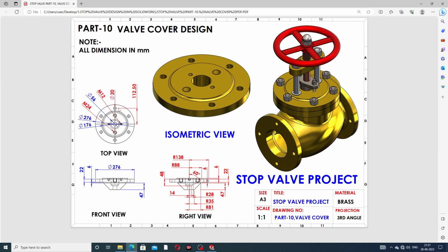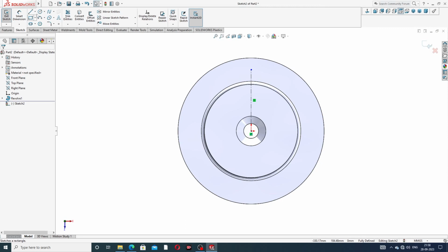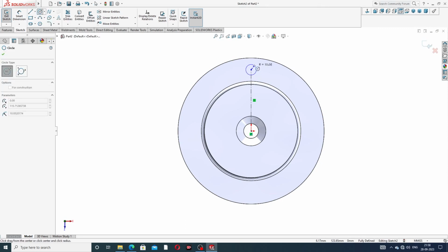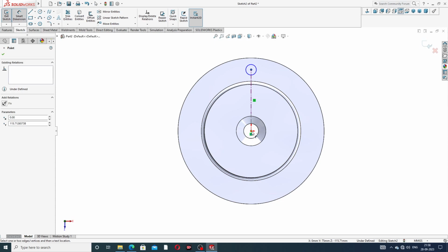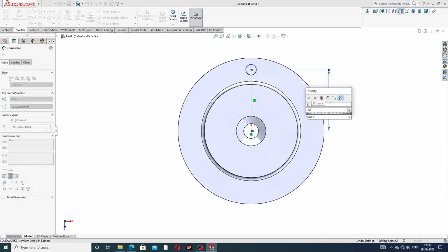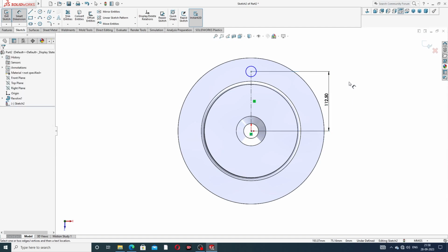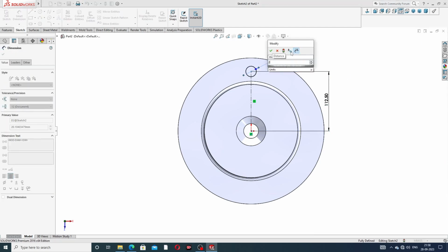Okay, and this is perfect and correct. And okay, this distance is mentioned here, but apply a thread, and then distance is 120. Okay, and use a circle drawing here, and this is a vertical line, and this distance, this point to this, is 112.5 millimeter, and this diameter is 20 millimeter.